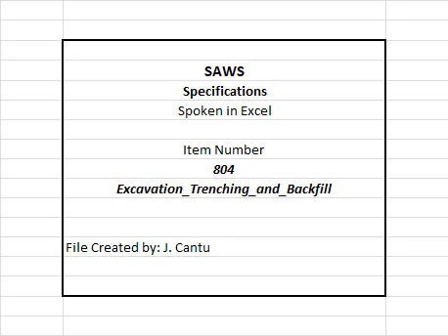B. Trenches shall not be backfilled until constructed structures or appurtenances, as installed, conform to all requirements specified. 1. Failure to comply will require contractor to re-excavate trench at no expense to SAWS. C. Where pipe is specially coated or sleeve/tape wrapped for protection against corrosion, care shall be taken not to damage the coating or sleeve/tape wrap. 1. Damage to be assessed by manufacturer and repaired to manufacturer's recommendation at no expense to SAWS.